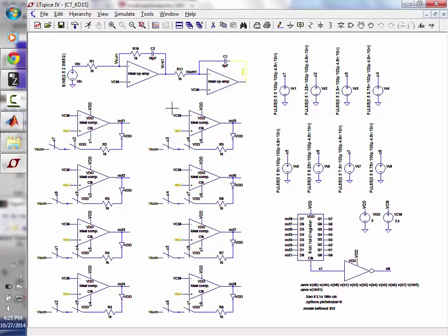I want you to do better than what's in chapter 9, because now you don't have the... see, here I'm generating my clock signals, I'm using everything ideal. If you get to 10 bits, that's really good, because with Spice there are numerical issues, so getting above 10 bits will be a challenge. I think you could probably play some games if you choke off the bandwidth a lot. But that's more MATLAB than anything else, because what you're doing is choking off the noise, filtering it out with a filter.